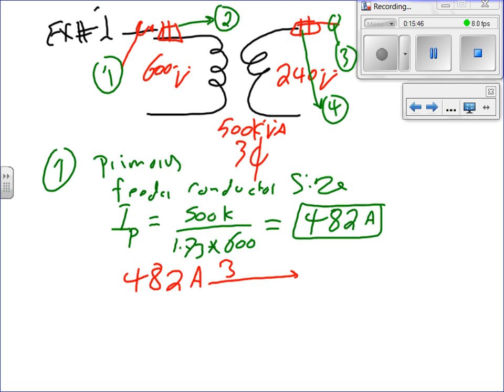All right, so I want to go directly and take my 482 amps. Where do you think I'm going to go? 310.16 table, and under which column? 75-degree column. I bet you by the time you graduate from here, you're going to learn that one. How many conductors and why? Let me just give you a hint, guys. On the primary, most times I have a delta. On the secondary, I have a Y. Would that give you a hint? Most of these transformers that we use in the building are delta primary, secondary Y. Almost always delta Y, almost always. But I have to tell you that because you need to tell me how many conductors I need.